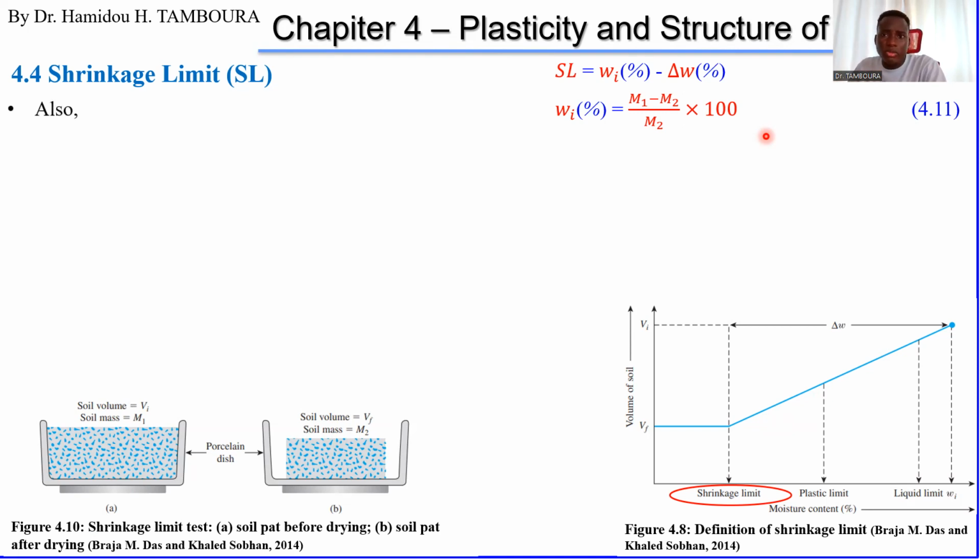Yeah. What do we have again? Now we will attack this one, this delta omega. This one can be obtained with this formula. How about this part, the variation of the water content? According to this same figure, logically, delta omega, delta W if you want, is just the variation of water content.